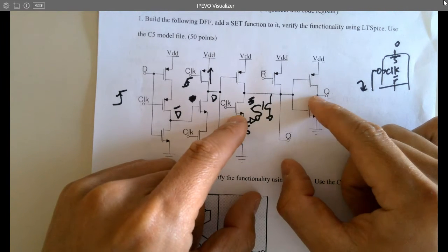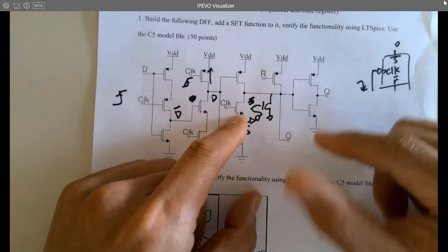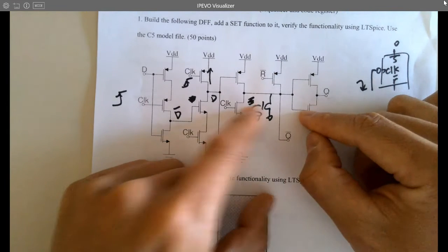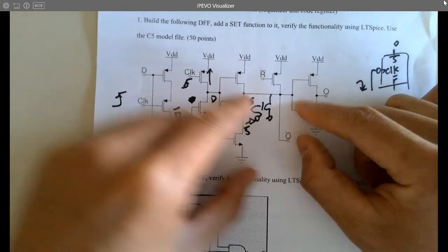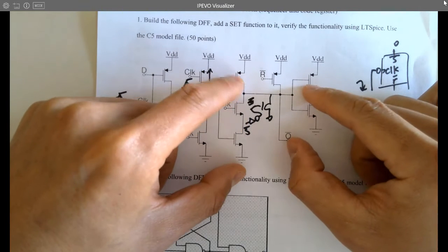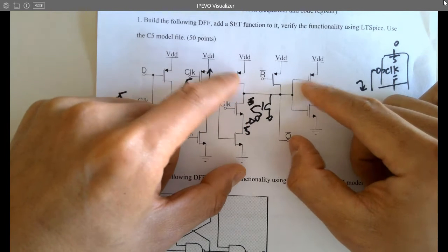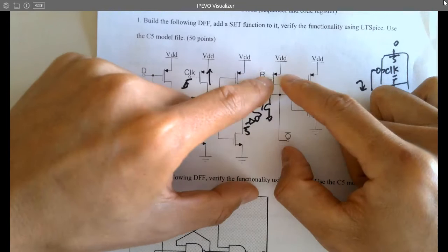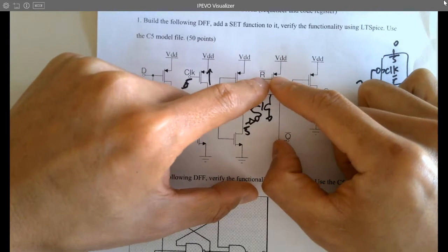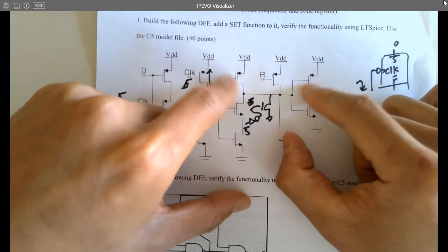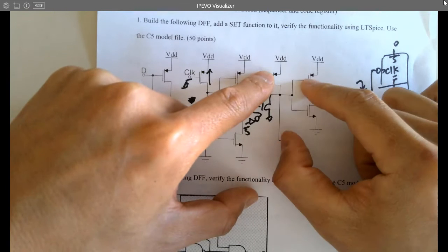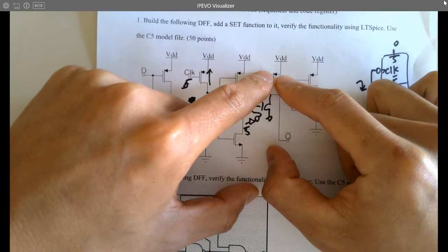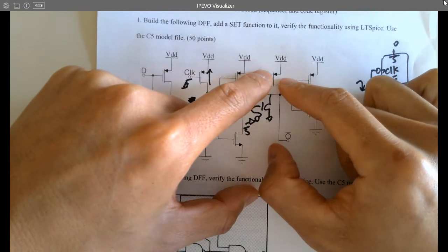We haven't learned that yet, but starting from next week, we're going to cover digital models. You'll see the gate has a capacitance. There are so many charges being stored in the input and output of the transistors. So you need a pretty strong PMOS to compete with all these other transistors, or to charge up all these transistors. How to make a strong transistor? Make it wider.